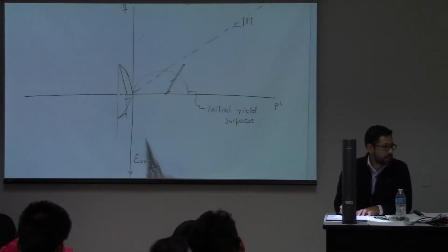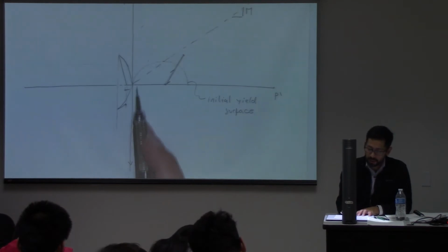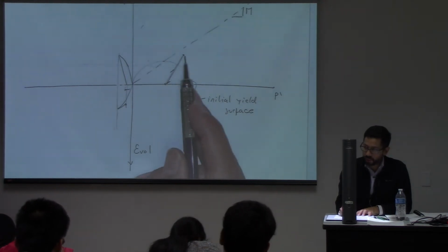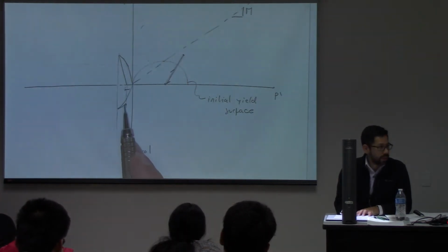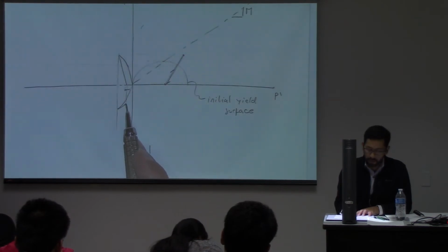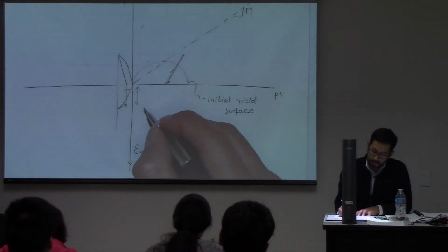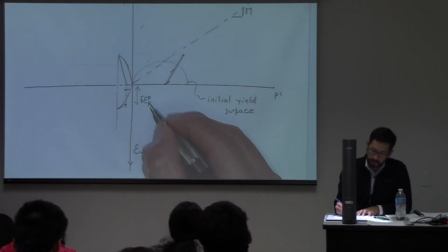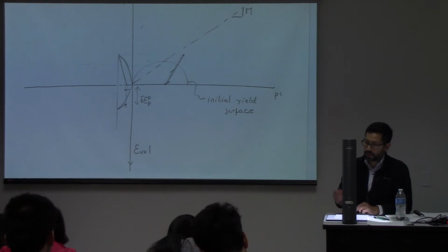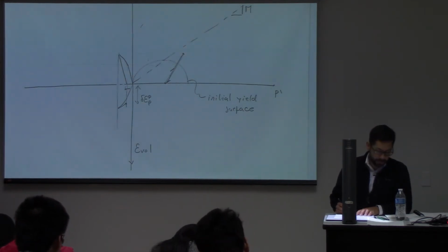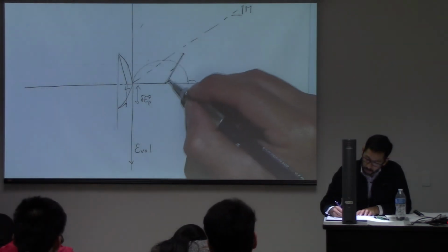But now look, I have a change in volumetric strain which is irrecoverable and was associated with going over the yield stress. So it didn't come back over there. It just came back over here, and this difference now is what we have changed. That will be your delta EPP, volumetric plastic strain. So let's load this material again.